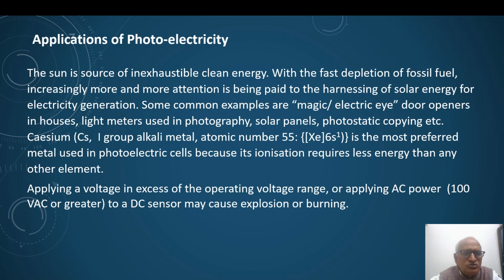Some precautions need to be exercised. For example, applying a voltage in excess of the operating voltage range or applying AC power of 100 volt AC or greater to a DC sensor may cause explosion or burning. So precautions are a must.